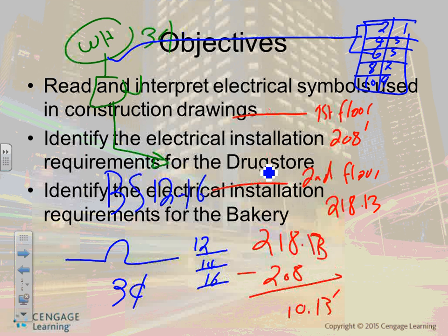Go all the way to E3, same thing. This is the second floor. Again, we will get into these in detail as we move on. So you have your receptacles, power and lighting, everything. What they did for this project is put the lights and receptacles on one sheet, and the low voltage separate. Our project will be separate. We will have one sheet for lights, one sheet for receptacles and power, and one sheet for low voltage. So three sheets. Again, we will go into these details.